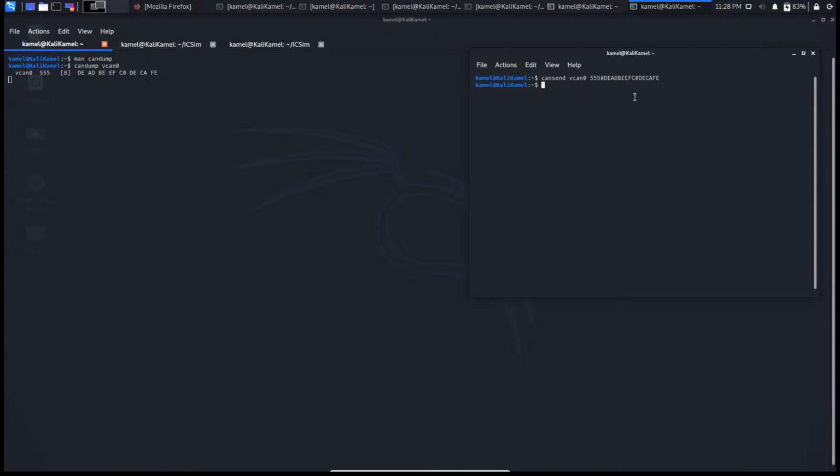So if you're ever plugged into a car, you have your CAN hardware and you're using open source CAN software, and you just want to see what would happen. Maybe if I send this message with this payload instead of this payload, because the car is sending this message with all zeros, what if I send all Fs instead, right? You just want to see what happens? Go ahead and send a message using cansend, right? Great way to do it. Very easy. Easiest way to send one CAN message.